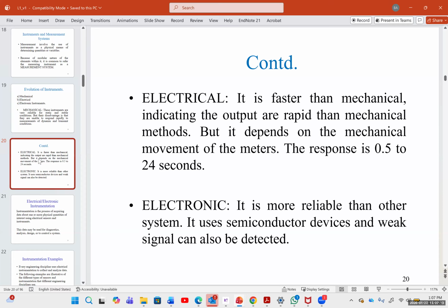The reason is if you have a remote sensor, like the example that I gave you for sucker rod pumps on oil fields, and that system is running on battery, you don't want it to measure every second or so, because you're going to run out of battery in a few days. And you can't go and change the battery every few days. That's the reason it goes into a hibernation mode. It turns on, it takes the measurements every 10, 20, sometimes every half an hour. So if you want to measure temperature, you can do it every 30 minutes. And that significantly increases the battery life of the system.